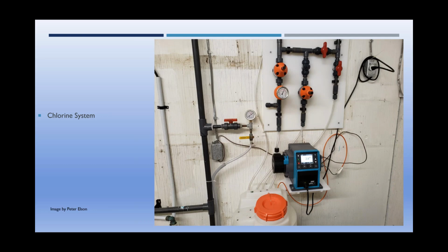So he would look through the glass. He'd see that the chlorine pump was running and he'd go about his business, but he wouldn't go in and actually look to see how much chlorine was being used. And of course, the problem was the system was airlocked. And for about 2 months, I think, he didn't bother checking it to see if it was actually using chlorine.